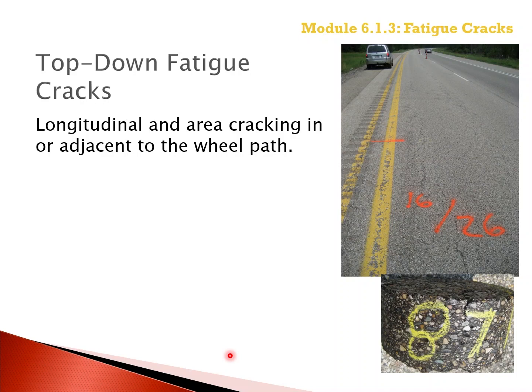Short longitudinal cracks can start shortly after construction. However, these longitudinal cracks sometimes continue to grow in the longitudinal direction and can take much longer to form the classical alligator cracks. These types of load-related cracks can initiate at the surface and propagate downward through the asphalt layer.